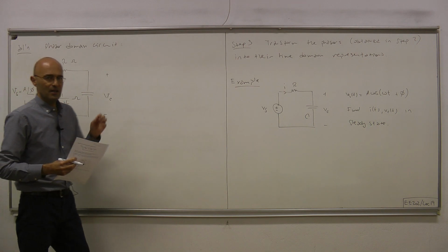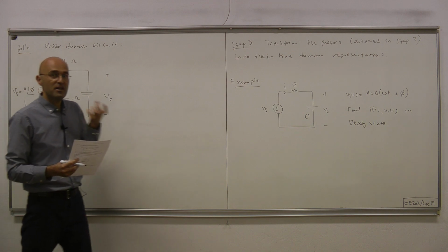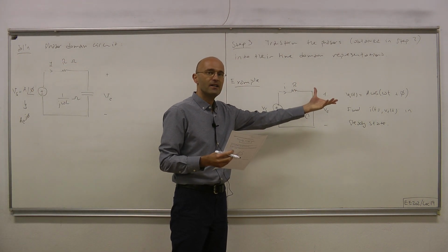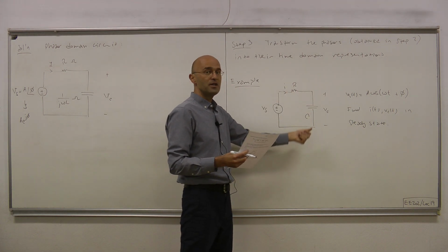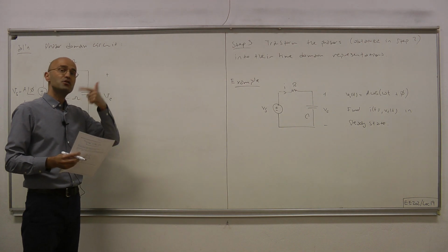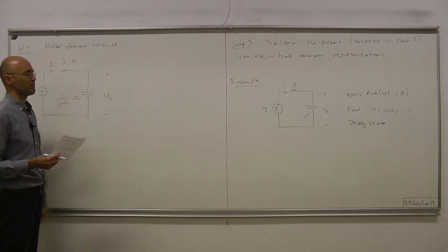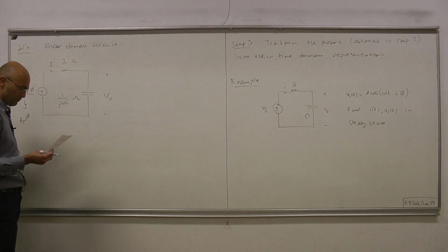The important thing about the phasor domain, or the simplification that the phasor domain circuit brings, is the following. Here we have farads, and also if we had an inductor, we would have had henries, but now we have no farads, no henries, everything is in ohms, because the ratio of voltage to current is constant.